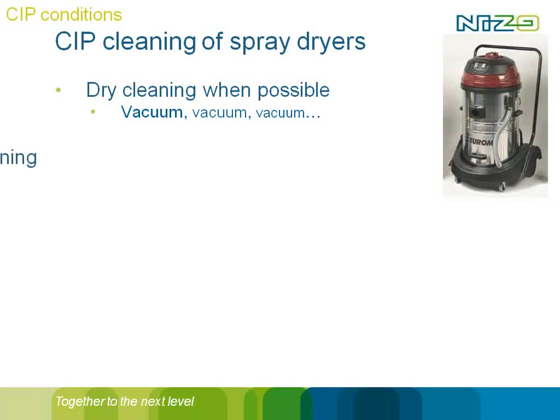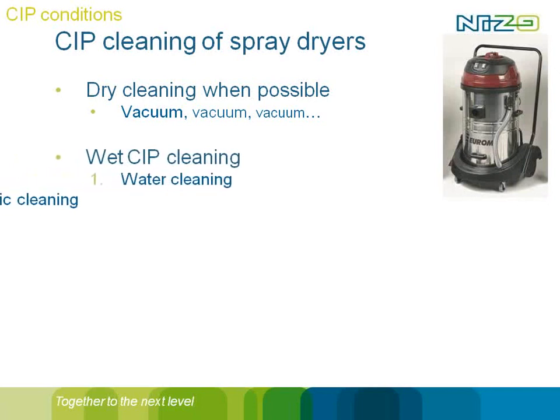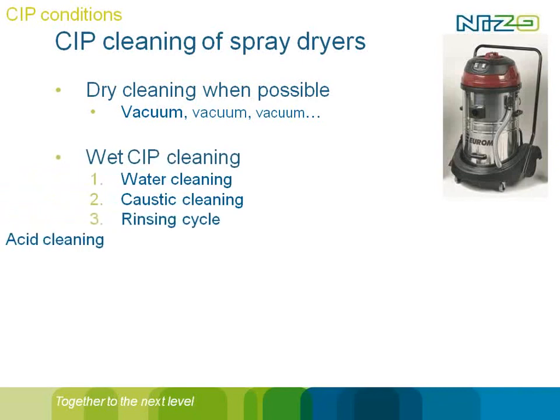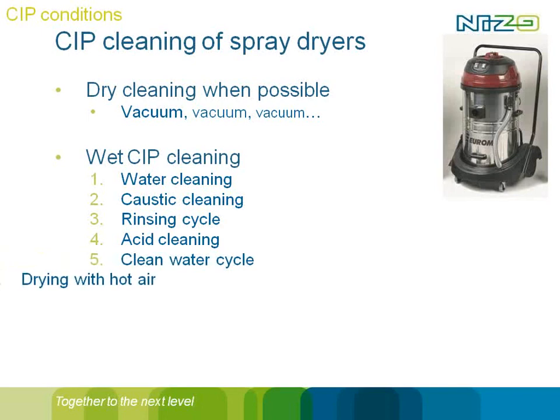If you do have to clean wet, and in some cases the type of tower, the cleaning tower, makes it necessary to do so, the way of cleaning is actually not different from a standard CIP procedure. But what's very important is that you do have step 6, which is drying with hot air. It's very important to get rid of all the